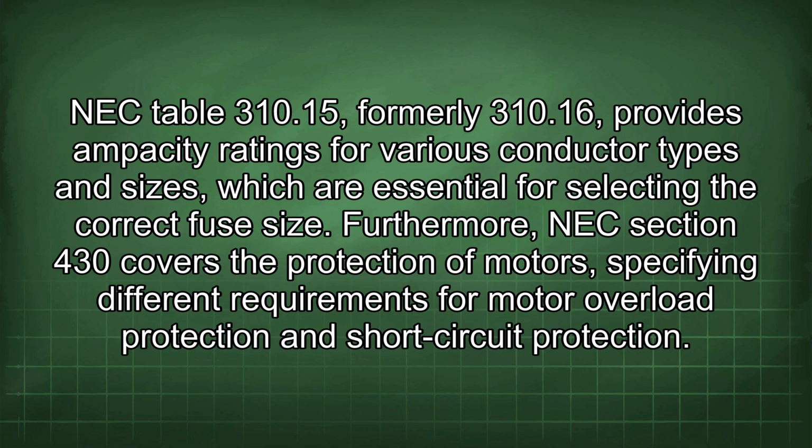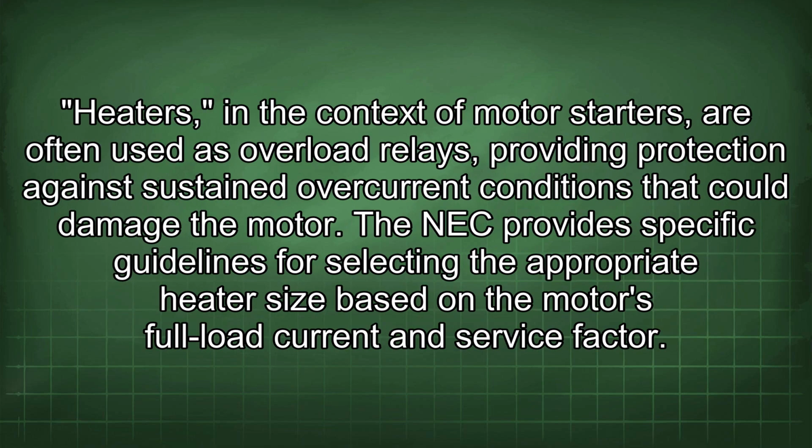correct fuse size. Furthermore, NEC Section 430 covers the protection of motors, specifying different requirements for motor overload protection and short circuit protection. Heaters, in the context of motor starters, are often used as overload relays, providing protection against sustained overcurrent conditions that could damage the motor.